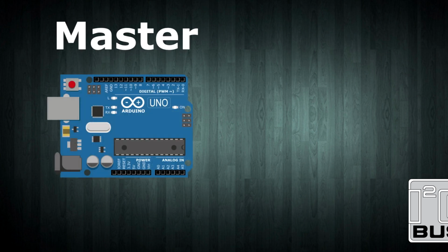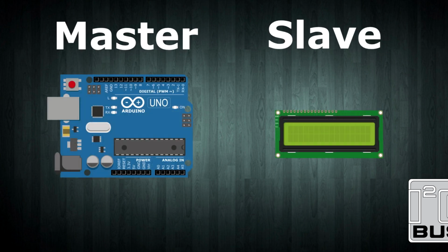Communication with I2C is also based on the master and the slave relationship. For example, while our Arduino board is a master, our LCD screen is a slave, and we control the slave through the master. In addition, each device used in the I2C protocol has its own address. For example, like 0x27. We will use an address like this when using our LCD screen. In this way, we will prevent data from being lost while transferring our data.